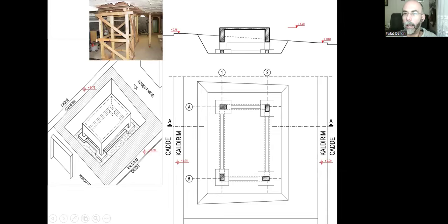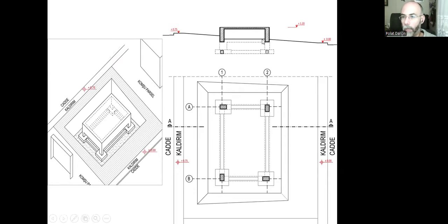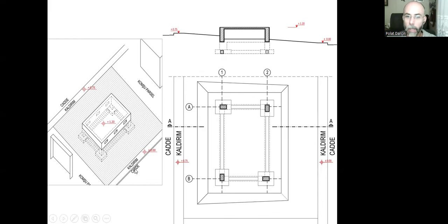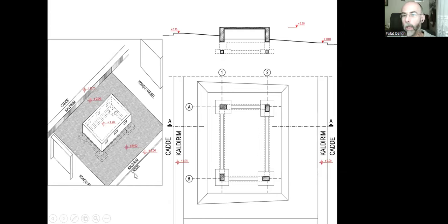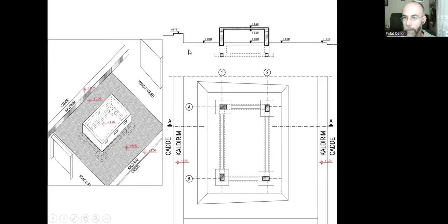And we can use, of course, dead shores. They can be there all the time. We don't need to take them out. And we can fill the earth inside and around the building, so there is no excavation pit anymore. And we can have our little windows to provide air circulation. And if we want, we can leave the area like that, or we can change the slope. We can excavate the area like this.